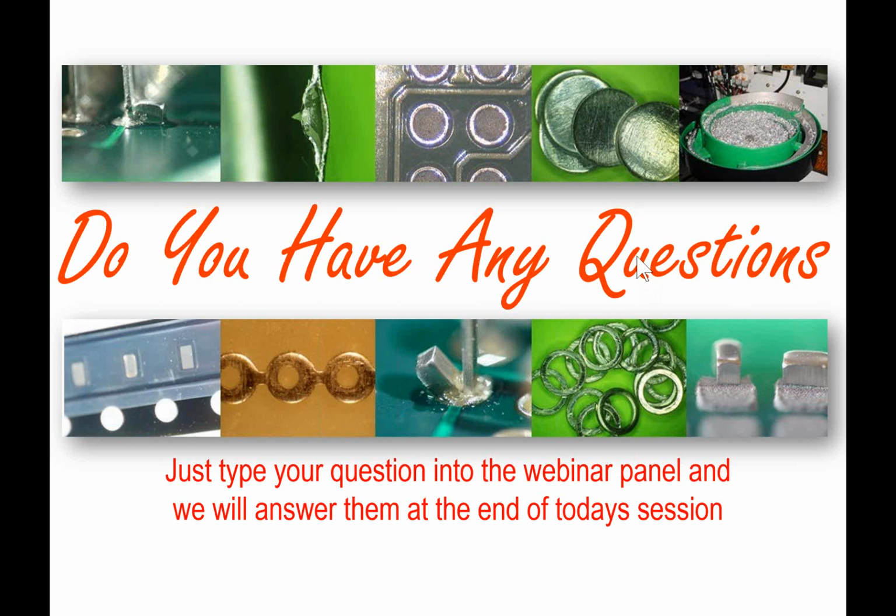I'm assuming you can't actually add this into the overprinted area of a solder paste, so it's not going to get drawn in. So that would be one solution. You could use a naked preform or alloy only, then place it into the solder paste deposit. There would be sufficient flux to make sure that that alloy was drawn in, as the video showed. If you couldn't use a flux in a solder paste, potentially you could use a deposit of a tacky flux or a gel flux, or you could even, in a low mix manufacturing sequence, dip your preform into flux before you start.